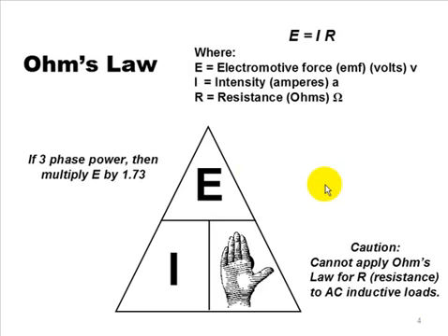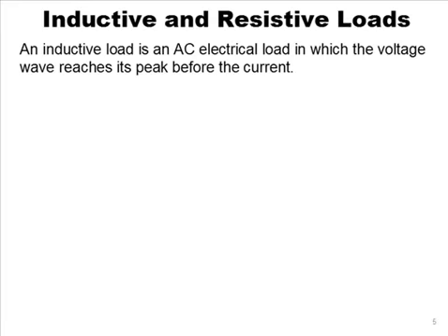Resistive loads, fine. Electric heaters, that kind of thing, everything is fine, because those are non-inductive. An electric heater draws the same amperage, voltage, etc. when it starts as when it runs. There's no inductance. There's no surge of power. And we'll talk more about inductance later on, but get the broad strokes here of Ohm's law. So I write E over IR when I sit down. The other thing I do, in fact, let's talk about this right now. I didn't realize I put it in a section.